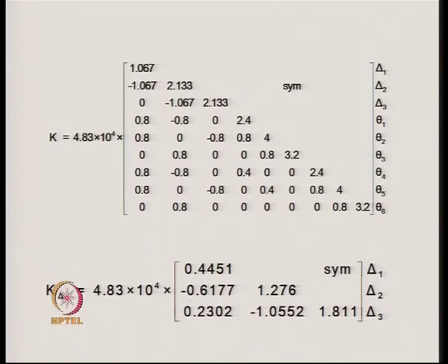In that case, we have made sure that at the bottom beam, or the first story beam, at the two ends of the beam, the moment coefficients will be equal to 0, because we consider them ordinary hinges. And after we have written down the total stiffness matrix, only then we condense out the rotational part of it and land up in the 3 by 3 stiffness matrix, that is the condensed stiffness matrix.